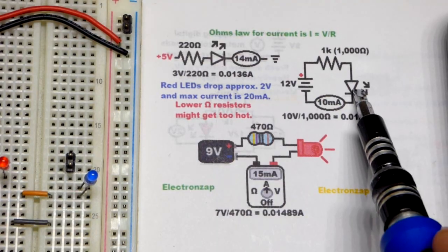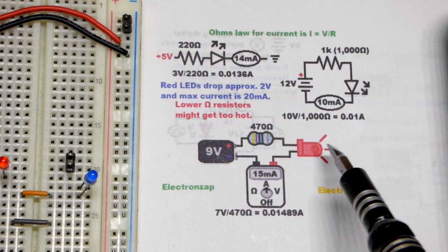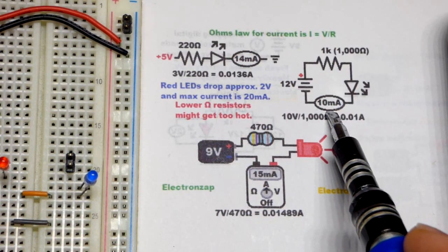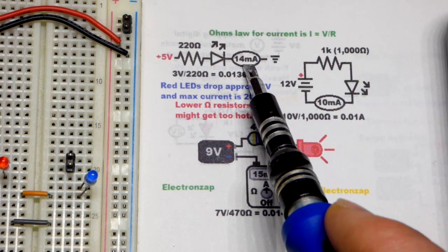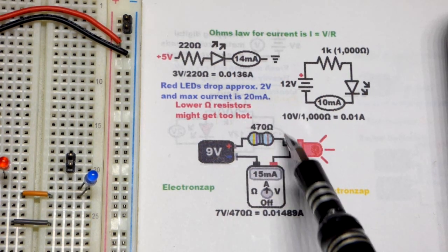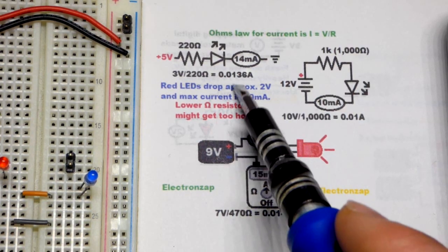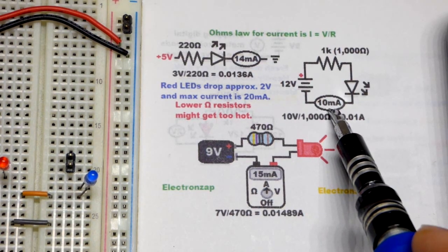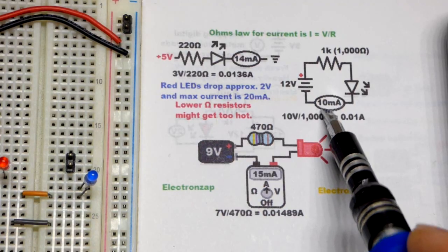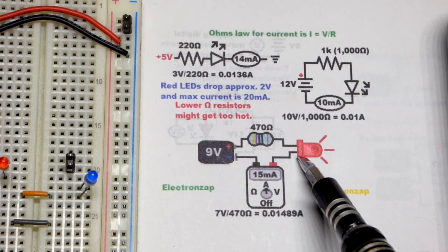LEDs in general, these indicator LEDs, have a limit of about 20 milliamps of current. And so 10 milliamps of current is probably fine. With these red ones, you might want a little bit brighter, closer to 15 milliamps of current. But when you get to about 20 milliamps of current, it starts wearing down how long they're going to last, and higher current is going to shorten their life even more. So generally try to stay a little bit above 10 milliamps of current for these red ones. The blue and the green ones are really bright. You can be at like 5 milliamps of current and be perfectly fine.